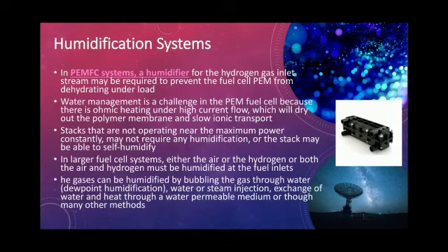Next is the humidification system. In a fuel cell, humidification is needed, such as in a PEMFC system. A humidifier for the hydrogen gas inlet stream is required to prevent the fuel cell PEM from dehydrating under load. Water management is a challenge in the PEM fuel cell because there is ohmic heating under higher current flow, which will dry out the polymer membrane and slow ionic transport.